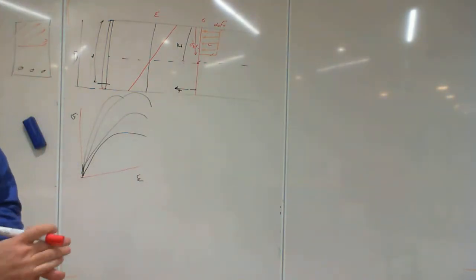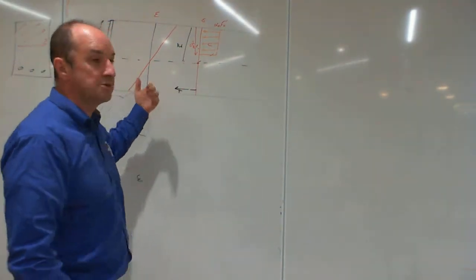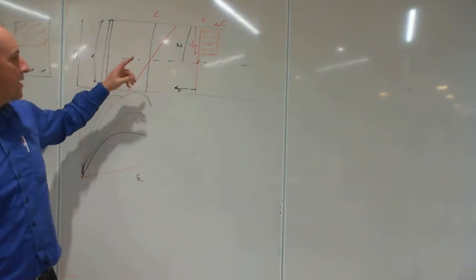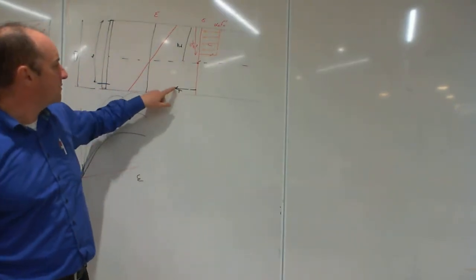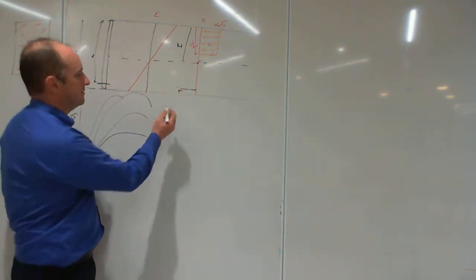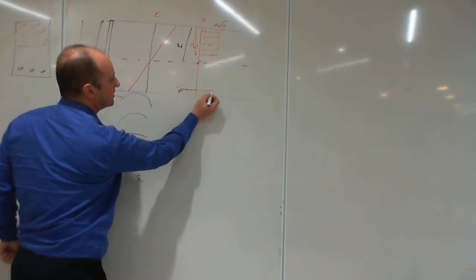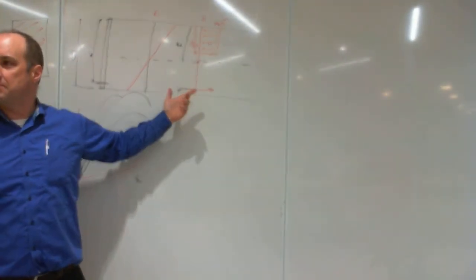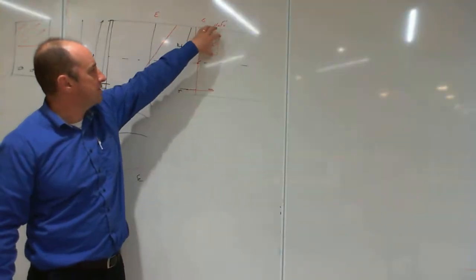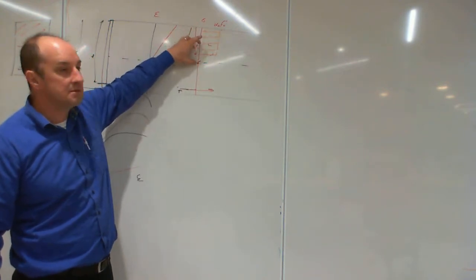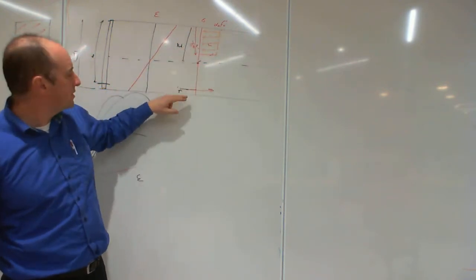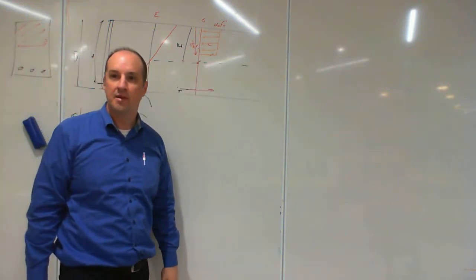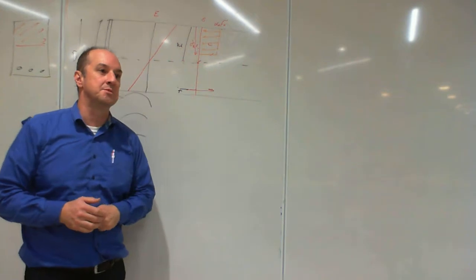So to summarize where we're at, this is all in the singly reinforced beam topic. I hope you'll forgive me that those arrows both go the wrong way. Let's do tension like that if you like. So they're going opposite directions. The bending moment capacity of our beam is that force times the lever arm distance plus that force times the lever arm distance. That's how singly reinforced concrete beams work.